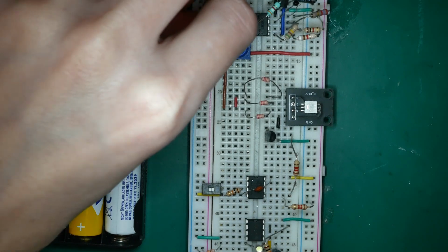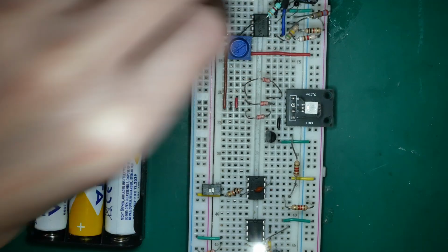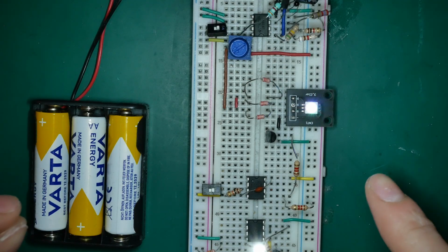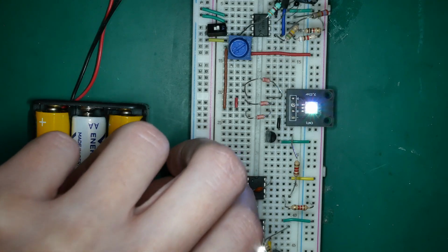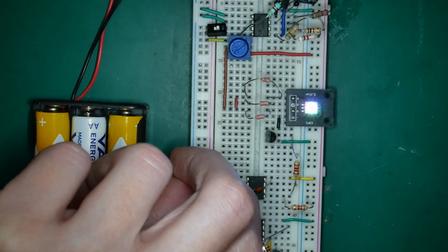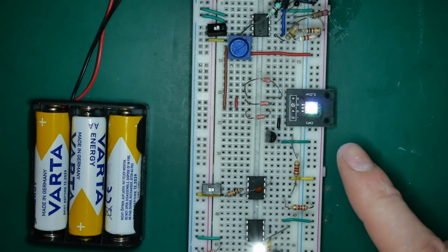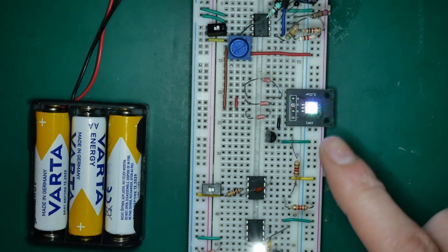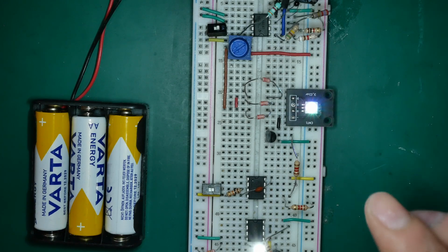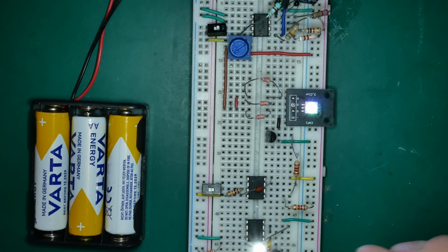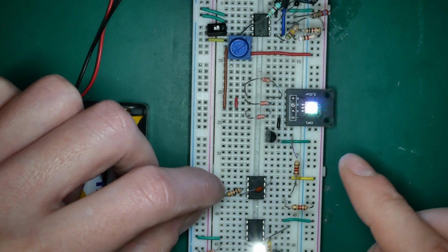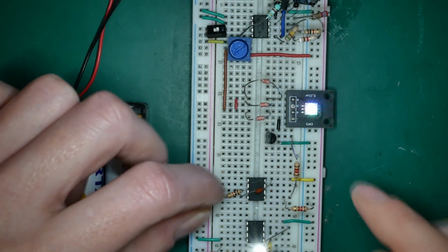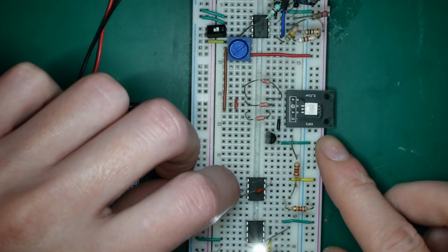Before moving on, there is one issue worth showing. When switching between modes, I was getting a small glitch, a brief flash on the LED. It only happened at the moment of switching, even though everything else was working correctly. The reason is how fast PWM behaves near zero. It doesn't always produce a perfect clean off state, so when the mode changes, a short unintended pulse can appear. At least I think so.